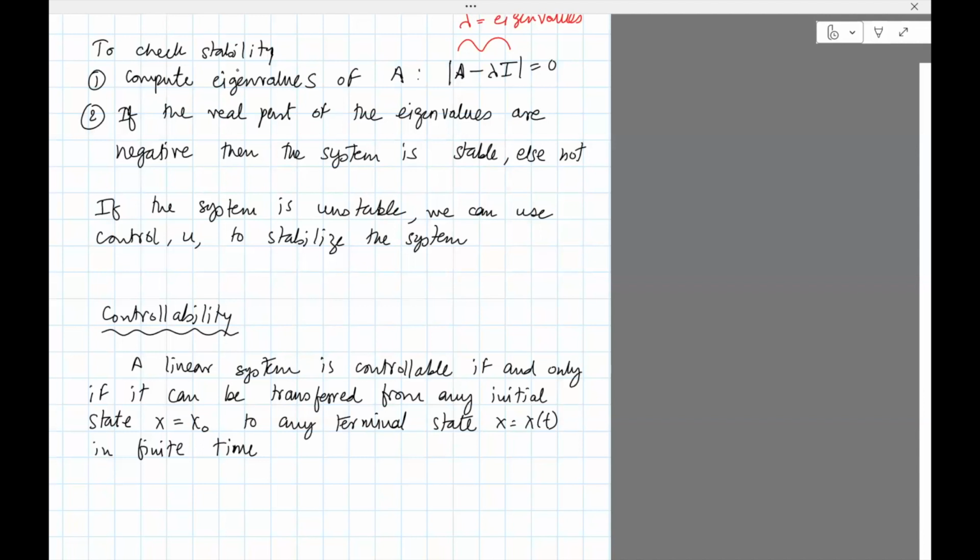It's a nice definition, but it really doesn't tell you how to check if a system is controllable. What this definition means is that you need to try applying U. The system is at some state x0. In the case of the spring mass damper, let's say it is at 0, 0. You just choose some condition, and then let's say you want the two masses to be at a different position.